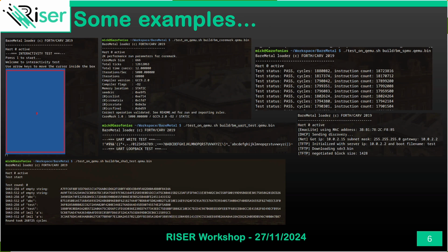This uses interrupts for the UART. And there is also a multiplayer version of this that also uses interprocessor interrupts, and timer interrupts. So we have a simple test that tests the core, the PLIC, and the CLINT. You test for external interrupts, timer interrupts, IPI interrupts, and see that everything is working properly with very, very simple code. If anything is wrong there, when you try to run Linux or something more complicated, it will be pretty hard to debug. So you better catch these kinds of bugs early on with such simple tests.